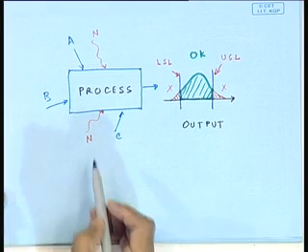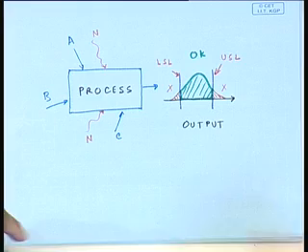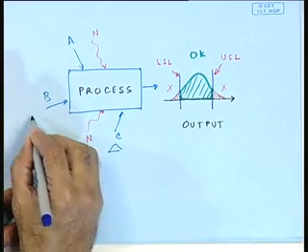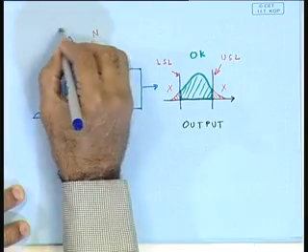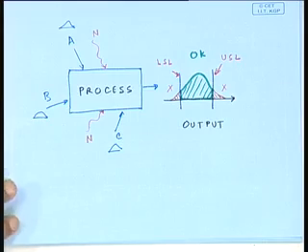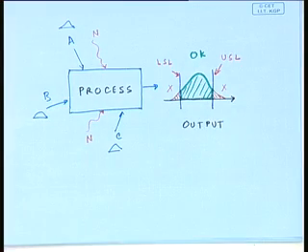And this can happen not only because of variations in the noise factors, which you are not controlling, but it's also very possible that the process variables themselves, they also have some variation. So each of the process variables that you set at the set point, they may also have some variation. And because of that, these variations impact the process, and the result is you got some inflated variation in the output of the process itself. Process capability, this phrase, is the measure of how well a particular process is able to satisfy or fall within the upper and lower specification limits. That's what really process capability is.